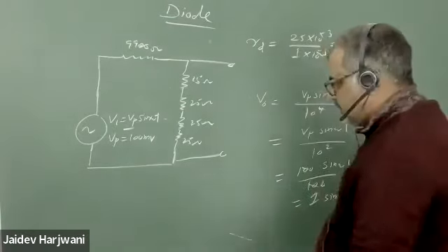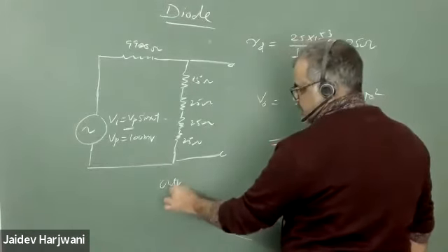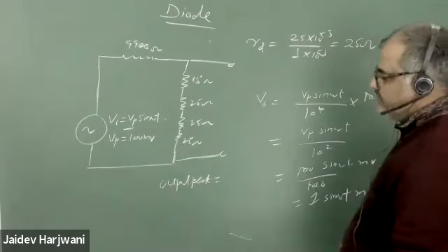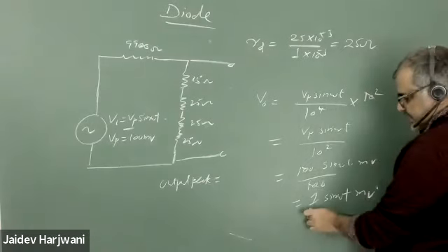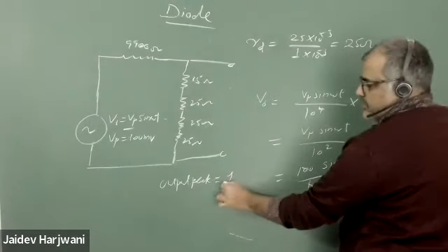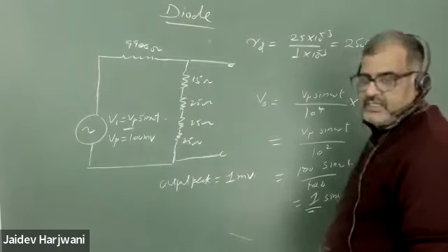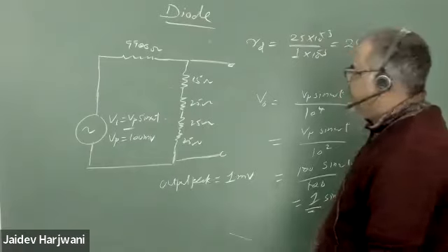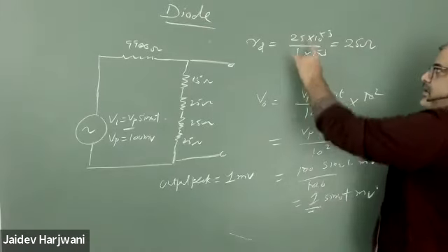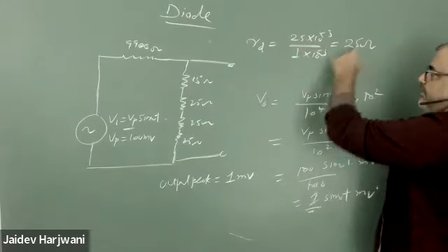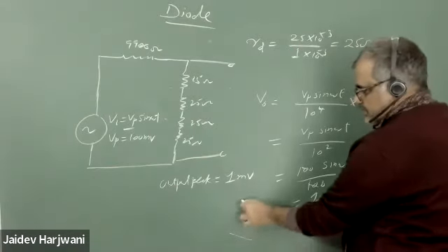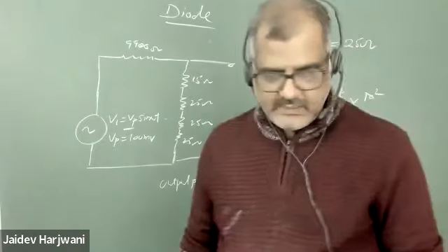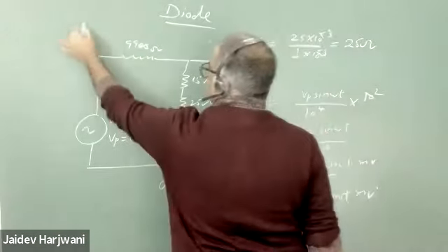प्लीज ये बताइए, यहाँ हमने आरडी के कैलकुलेशन में 25 इंटू 10⁻³ कैसे लिया? 25 millivolt है ना. So output peak they are asking, output peak that will be your 1 millivolt. आपका RD, formula क्या है? Eta VT upon ID. हाँ VT is 25 millivolt, this is milliampere. Okay, so this is your answer. This question came in GATE EC.